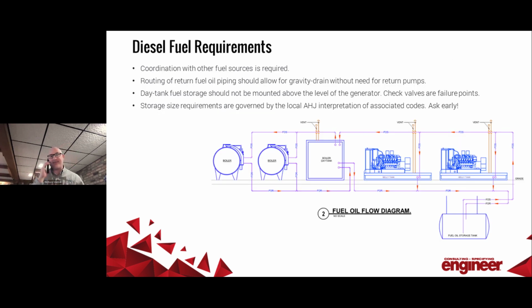Now, when you're doing systems like this, you might run into fuel oil if you're doing diesel. You're going to coordinate with your mechanical engineer for your fuel oil system, and they might actually serve boilers if you're looking at a hospital that has backup. The takeaway here is make sure you eliminate opportunities for single points of failure within your fuel oil system, such as allowing for gravity returns of your fuel oil and making sure that the supply side doesn't drain back and overflow any of your tanks.